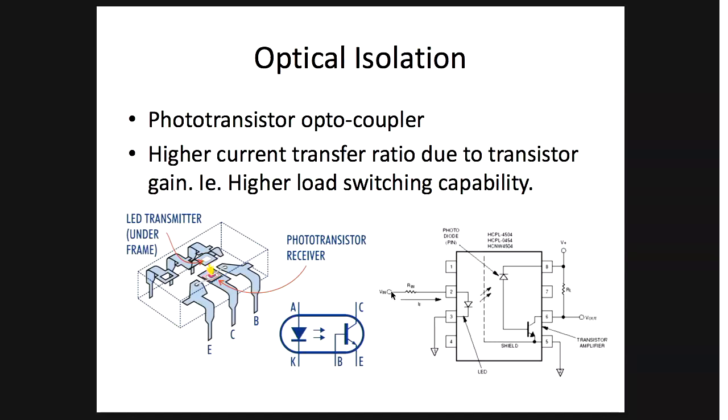How it works is, here you are giving your signal like this, and here this is the DC voltage. Suppose this is a DC voltage, this may be 5 volt. When the 5 volt is connected, this LED will be on. When this LED is on, the light will go, and here there is a photodiode.